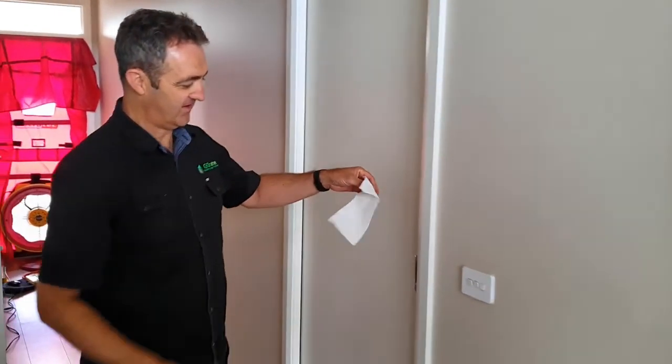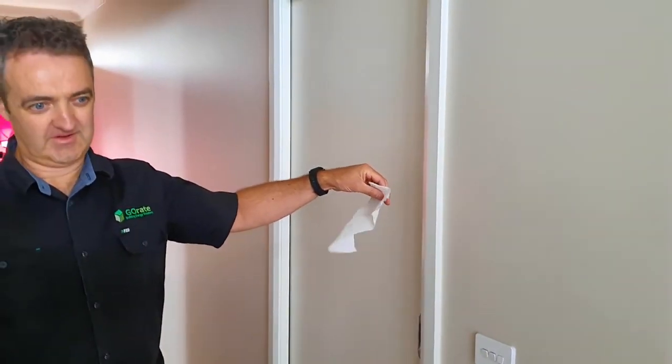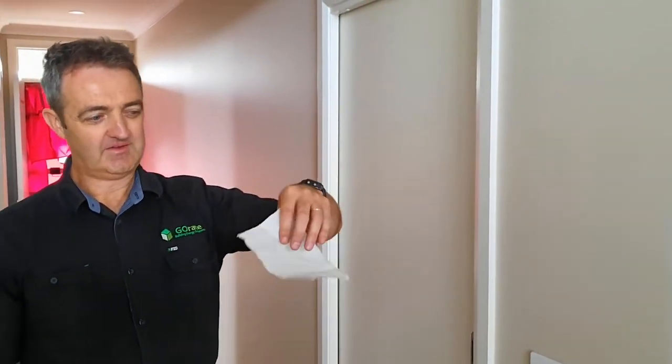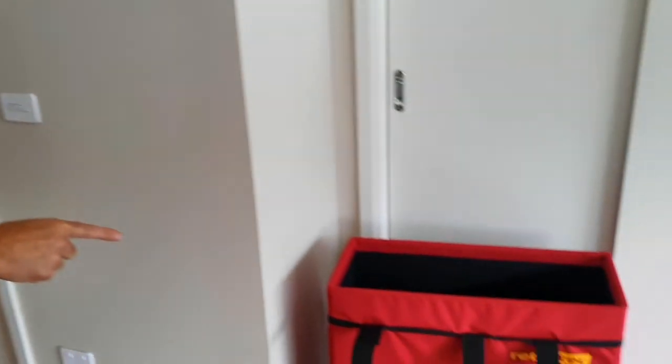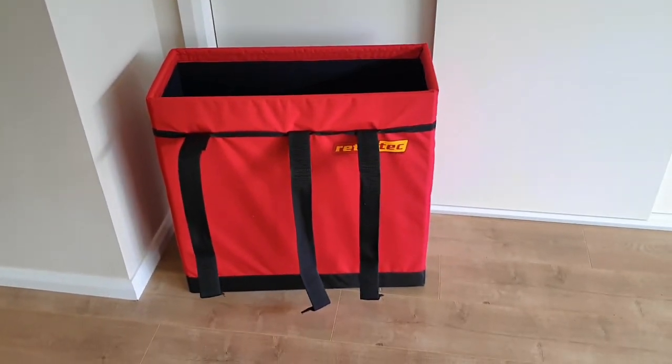Now we're having one last wander through the house with the fan turned up to about 85 pascals. Now there's a fair breeze coming through, so if we look again at our cavity sliding door, it's pretty bad. Just in general going through the house, we've got a lot of air. If you even look at the box here with the straps on it, there's a lot of air coming through. We'll wander through to the bathroom and you'll even hear the exhaust fan, which is not turned on, but you will hear it running.